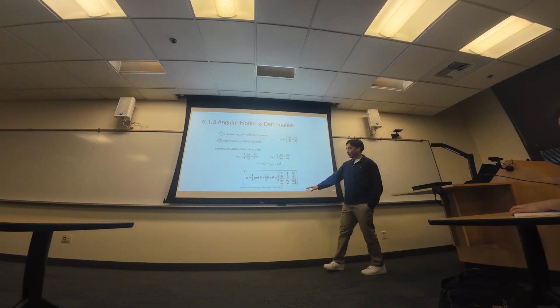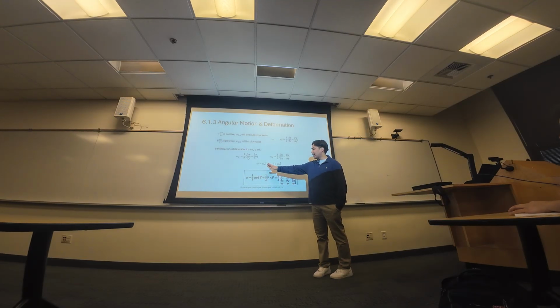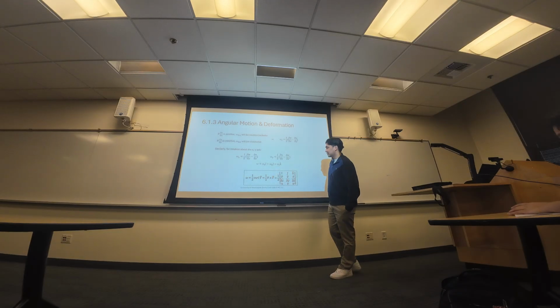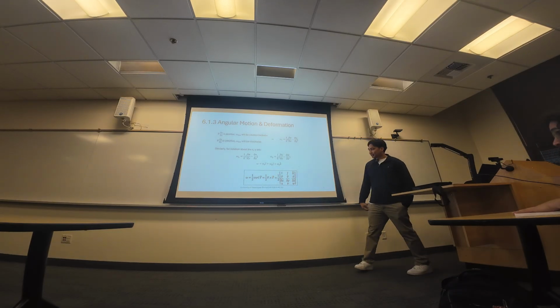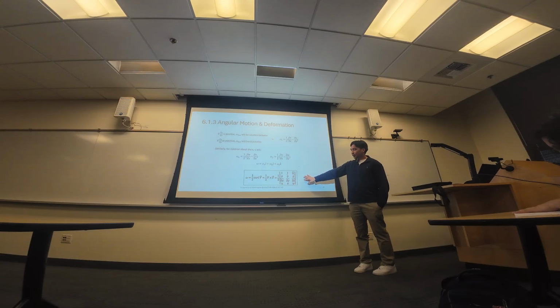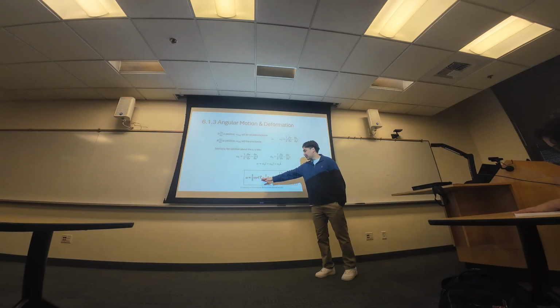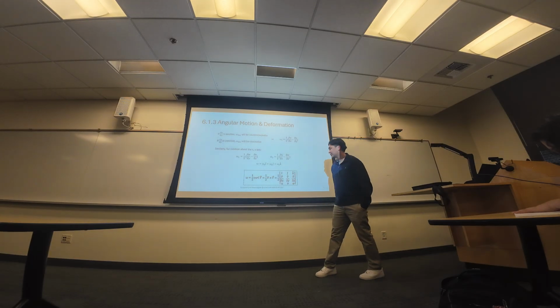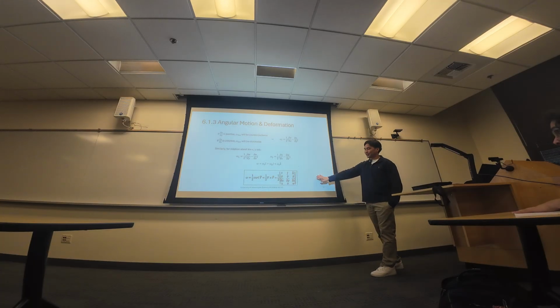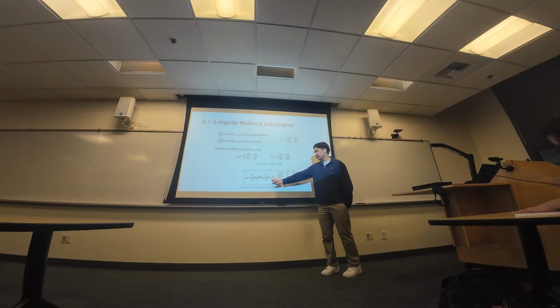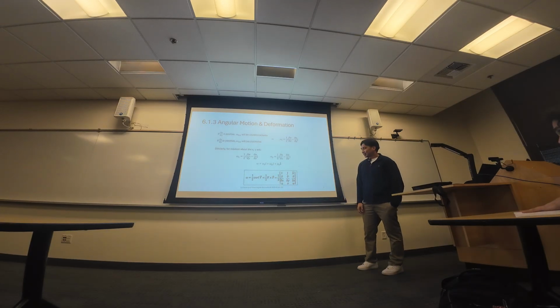And then if you wanted to combine your omega in all three directions, you have i, j, k, x, y, z. And this is an important equation where your omega, angular velocity, is half times the curl of the velocity vector here. I'm going to show you how the cross product works. Curl is essentially the cross product of your del operator and velocity. I think this was a lot of Calc 4 stuff. When I took Calc 4, this was really in there heavy, if you happen to remember.